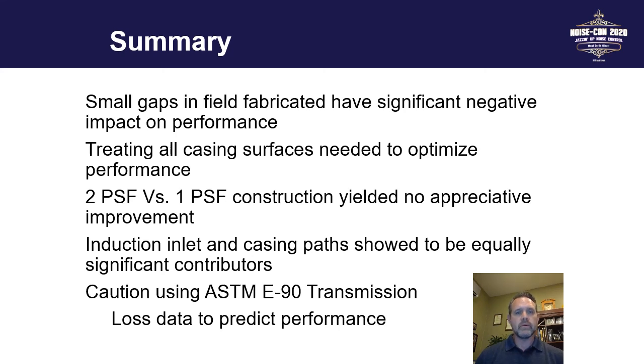So it's important to make sure that you treat both paths, particularly if the terminal unit has an open induction inlet. Treating just the casing, right, isn't going to give you a maximizing of the performance. You really want to look at treating both of those.